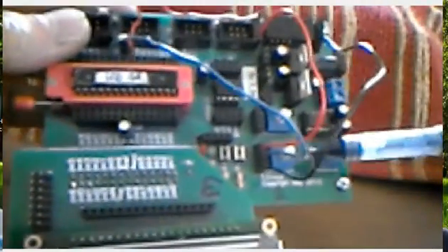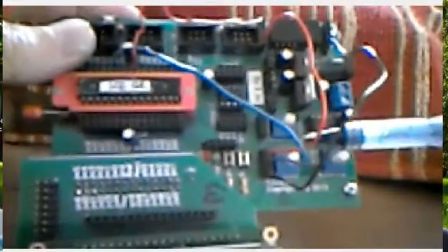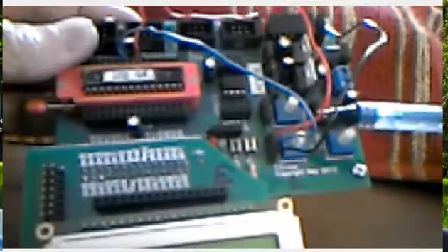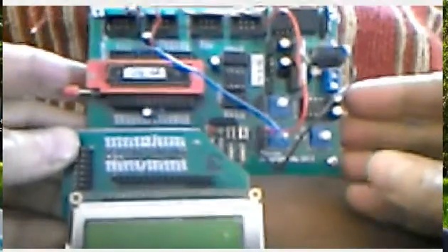This potentiometer is being tapped in the middle, going to PC0. On the outsides of the potentiometer, at the bottom and the top, we have a 5 volt wire here, and this wire here, the black one, goes to ground. And that's all you really need for doing this particular experiment.